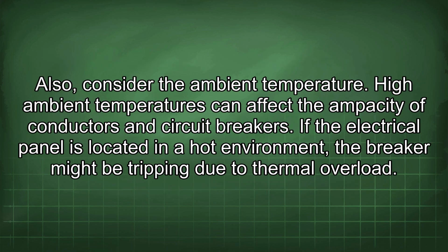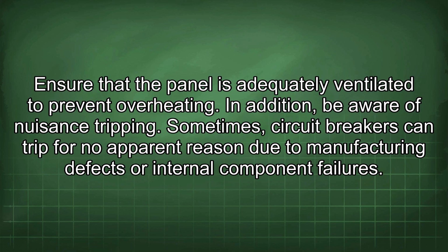Also, consider the ambient temperature. High ambient temperatures can affect the ampacity of conductors and circuit breakers. If the electrical panel is located in a hot environment, the breaker might be tripping due to thermal overload. Ensure that the panel is adequately ventilated to prevent overheating.